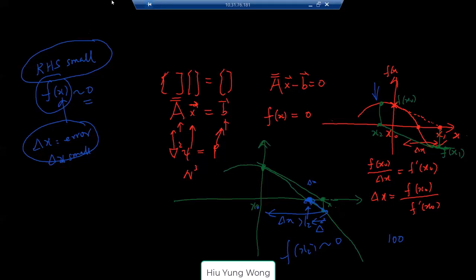Any questions? Do you have to do both of these for convergence or just one? You have the ability to choose both or one of them. But you want to be careful. Sometimes you can have very large RHS but very small delta x, or vice versa. So you need to be careful. But at this moment, I don't expect my students to work with convergence because this is a very difficult topic. So don't worry too much as long as you have a typical setup.